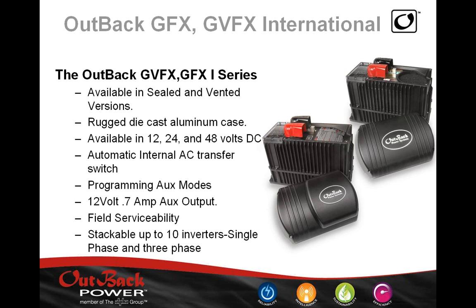If that generator deviates from what these inverters are programmed to look for before they accept an AC source, then it's not going to work. And I've seen that happen too many times, unfortunately, where someone buys a grid interactive inverter only to find out that it's not going to play with their generator. By the way, all the grid interactive models begin with the letter G. So here we have GFX and GVFX. This is a grid interactive vented FX inverter, and this is a sealed grid interactive inverter.